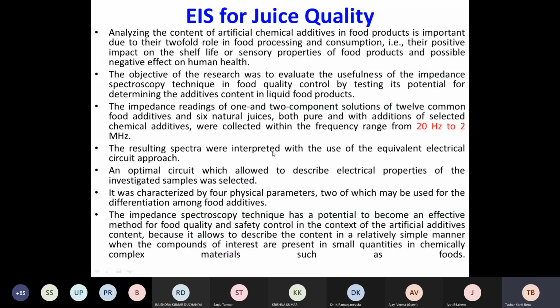So chemical identification on a microscopic scale is also possible if we have microfluidic techniques, and if we have the fluid sample, either the juice or some liquid food mixed with preservative or any other beverage, then we can put it in the microfluidic channel, and we can conduct impedance spectroscopy, and we can get the variation in the impedance.